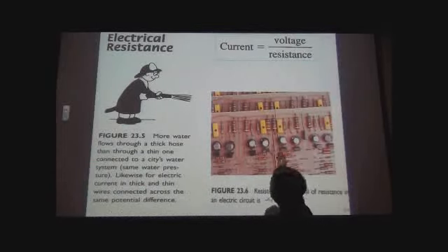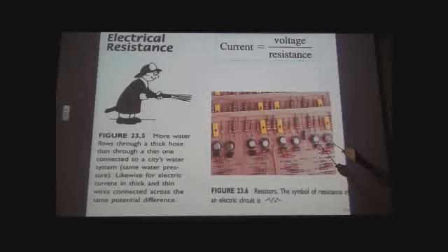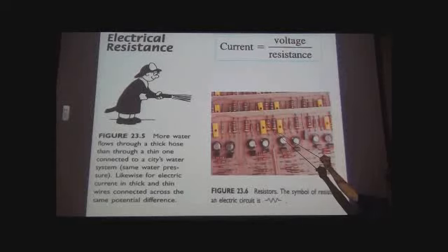So here's an illustration of a circuit board that has resistors. These little units that have these painted lines on them are resistors. Current can come in here, it experiences the resistance, and it goes out here. So the higher the resistance, the lower the current that goes through for a given voltage. What these different colors mean is just a way of reading. It was a way in the past for people to read the value of the resistor, right? Each of these bands, each color, meant a number, like 1, 2, 3, 10, whatever. So you could read this and tell how many ohms or kilo ohms or whatever this resistor was.